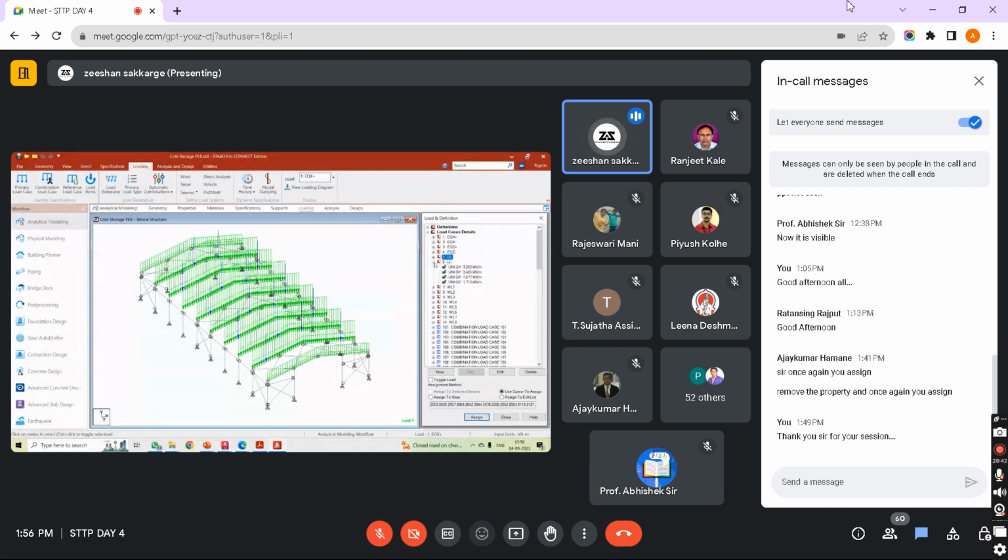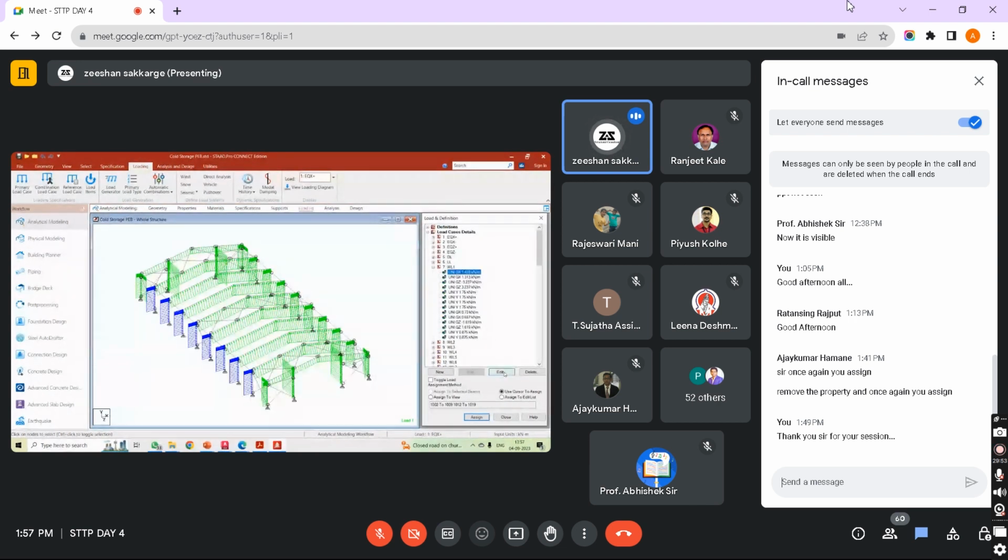Then we have these live loads. Again, as per IS code, we have different live loads on the roof based on the inclination of the roof. For wind load, it's very critical. For all the four sides of the wall, I have my wind. You can see wind load over here, then this direction away from the structure, then my loads on my rafters. These are inclined loads.